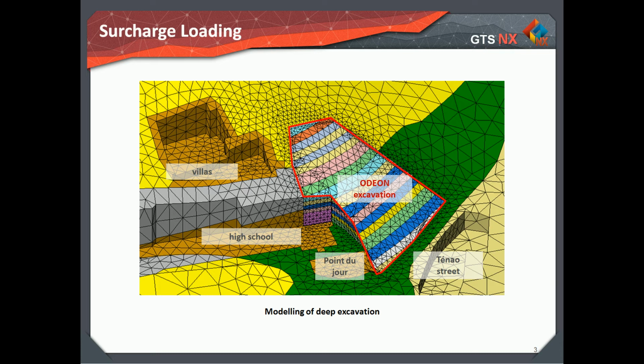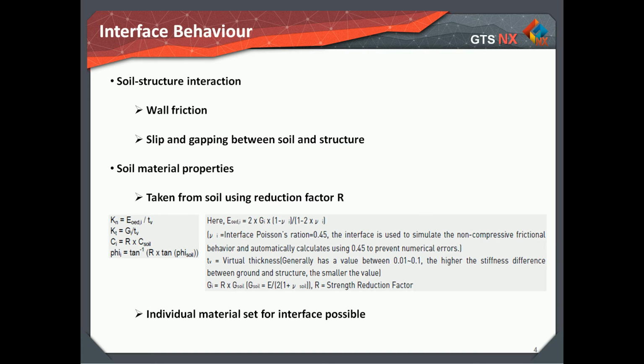There is no doubt that the building stiffness alters the pattern of retaining wall and ground movement over the greenfield situation. In any soil structure interaction situation, relative movement of the structure with respect to the soil can occur. The use of continuum elements with compatibility of displacement in a finite element analysis of this situation prohibits relative movement at the soil structure interface. Nodal compatibility of the finite element method constrains the adjacent structure and soil elements to move together.